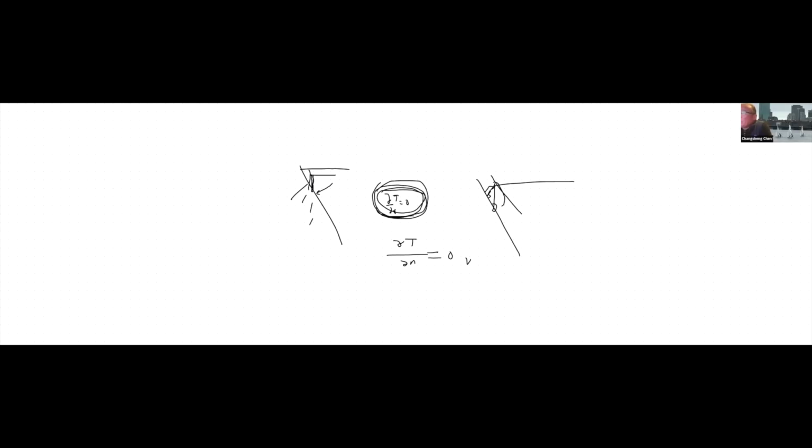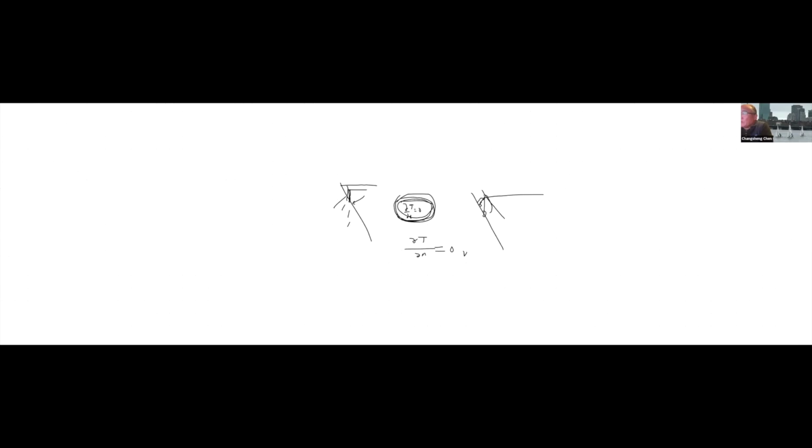We had a paper comparing with the other model, against FVCOM. We do find that the other model overestimates the upwelling relative to the analytical solution. The reason is the boundary condition they use, which is equal to this one. But we use this one, so we can reduce the upwelling, provided we have enough resolution and time, so it's not a sigma error issue. We were talking about not only sigma error: you can guarantee small sigma error, but the boundary condition can still cause another issue.